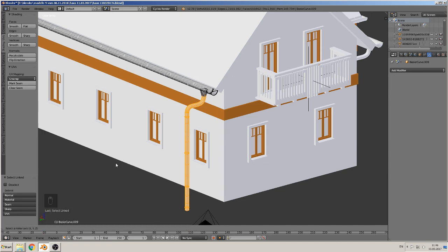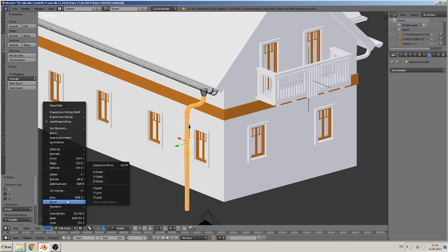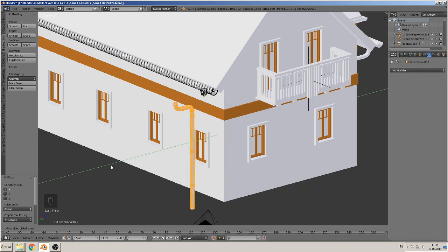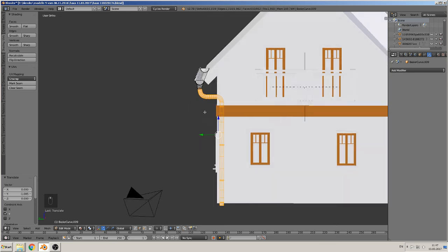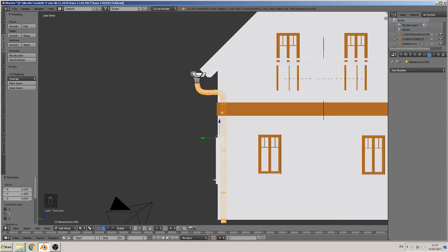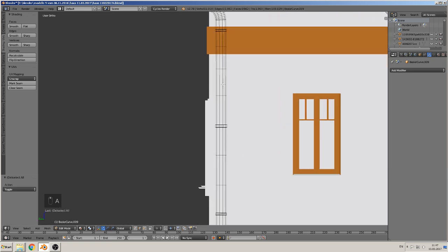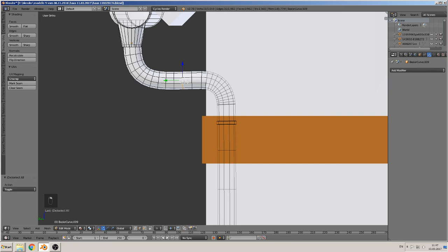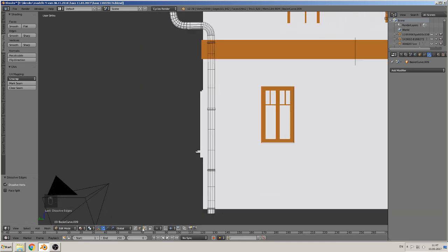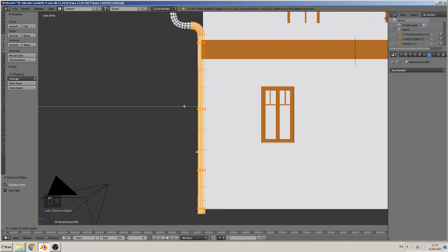Okay. Then we mirror that. So no, other way. Mirror again, interactive, hold middle mouse wheel and accept with left, and now we can get it on. We see we have here another whiteness from that. That means we can mark that and dissolve edges to get them away. Here too. And then we can mark that all and bring that to position. So we mark now that here and bring that out.